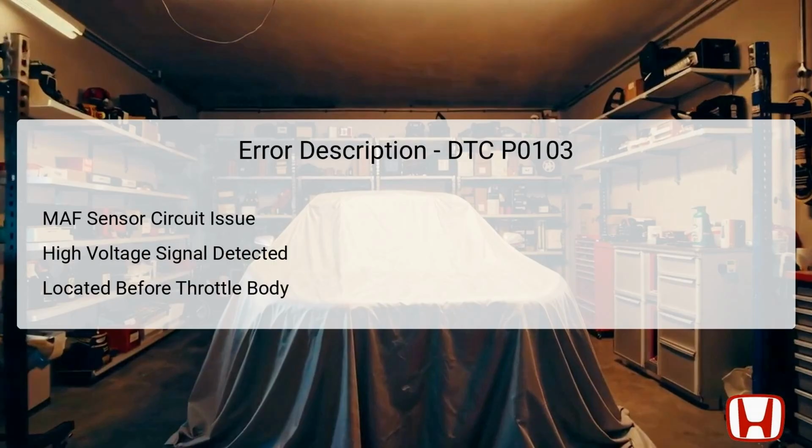The DTC P0103 points to a critical malfunction within the MAF sensor circuit. The MAF sensor plays a vital role in measuring the volume and density of air drawn into the engine, providing data essential for the ECM's fuel adjustment calculations. This code indicates that the MAF sensor is sending a voltage signal that exceeds 4.89 volts, thus flagging it as an operational issue. Located in the intake system, this sensor is usually positioned upstream of the throttle body, which means any faults could significantly affect the quality of air entering the combustion chamber.